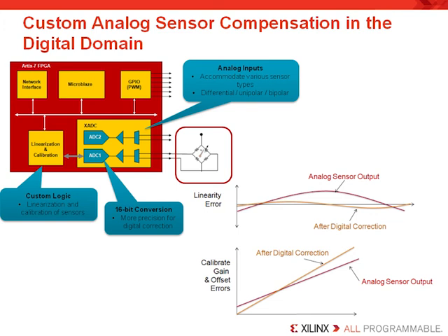Linearization of a large number of channels is very efficient to implement in an FPGA because the same resources can be shared across all channels due to the high clock rates that can be achieved inside an FPGA. The oversampling capability of the ADC, up to 1 megasample per second, and the ability to implement digital filters with a range of response types, along with any stop and pass band requirements, can greatly reduce the analog filter requirements. Simple passive low-pass filters can be sufficient to suppress higher frequencies and prevent aliasing effects.